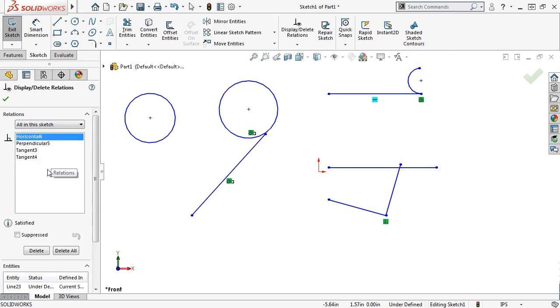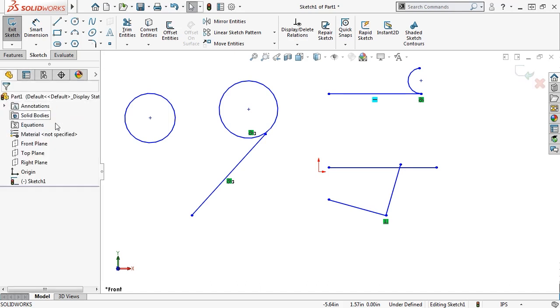One more useful option here is this drop-down list. We'll learn later that geometric relations fall into several categories. This list allows you to filter out only certain types. It's very useful when working with sketches to be able to see the relations between sketch elements. So the geometric relation flags are very helpful.